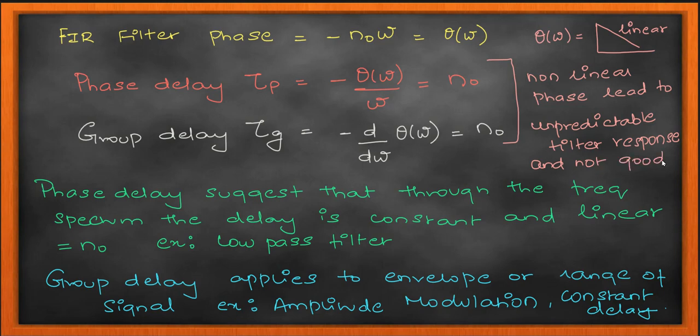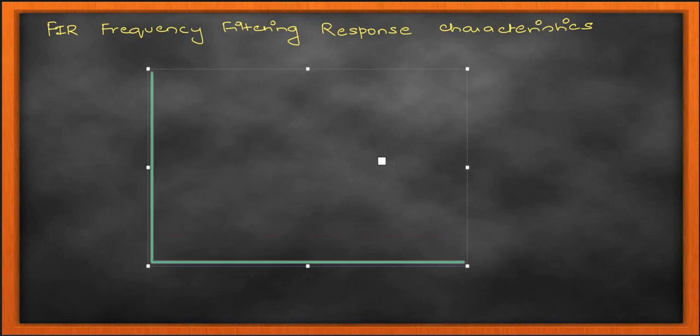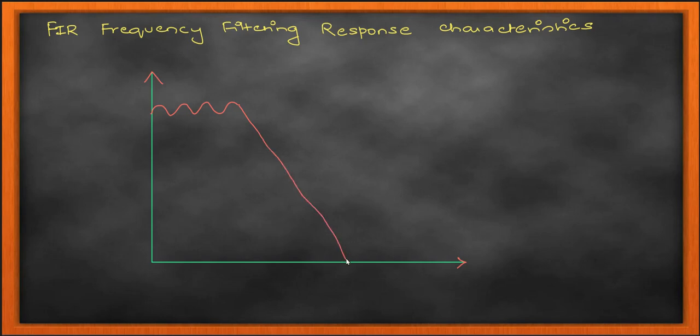So if you have a nonlinear phase, then what happens is your output will be coming with a delay of 10, then a delay of 12, then a delay of 14, which means whenever there is this delay, it is going to change your frequency. The frequency of your output is also going to be slightly altered each time this delay changes, and that is going to make your filter unpredictable, or the performance cannot be good because it's affecting your input signal's frequency. So that is your linear phase characteristic, very important.